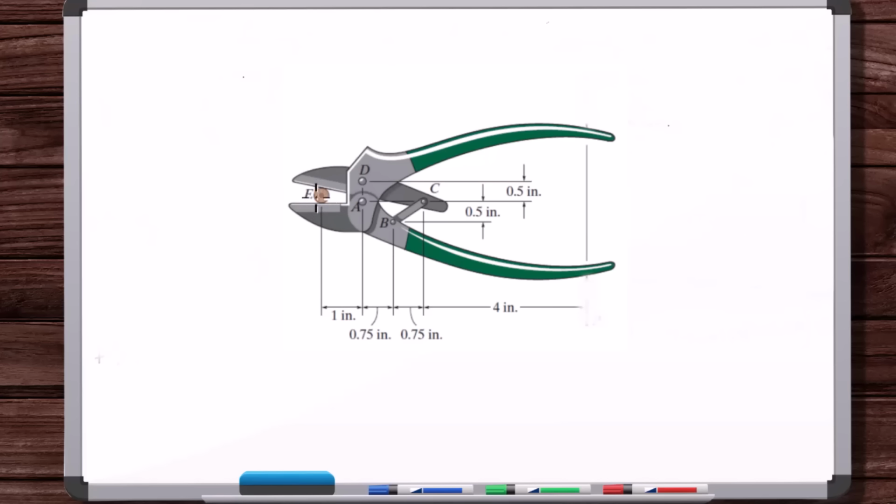Now, that might be confusing. How is it including the twig? That's a rigid connection, at least at this snapshot in time it is, right? Right at this point when you're shearing, this entire unit is a rigid body. You can apply forces of the magnitude of a hand pushing down, and the geometry doesn't change. So you can bring this entire assembly, the twig plus the shears, into empty space. Now that it's in empty space, remember, when we bring it into empty space, there's no forces whatsoever. We've just taken it out of where it's at and removed it from its environment.